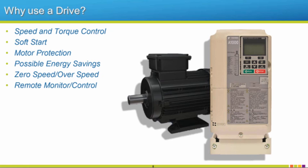So with the drive, we can now control the speed of our motor and in some cases even the torque, depending on our control method. We have soft start capabilities, and this is going to help us to not have excessive inrush compared to starting across the line. This will also lead to a less harsh jarring environment on the rest of our supporting equipment. Built-in motor protection, so you can protect your investment. And also we have the possibility of energy savings with a lower speed available and/or variable torque application. So possible energy savings.